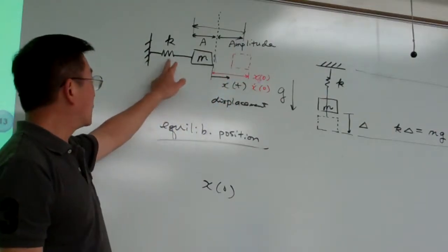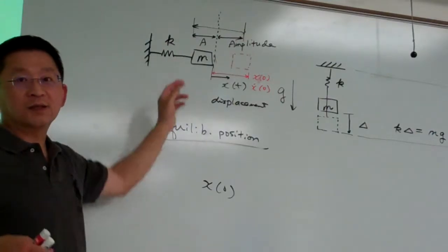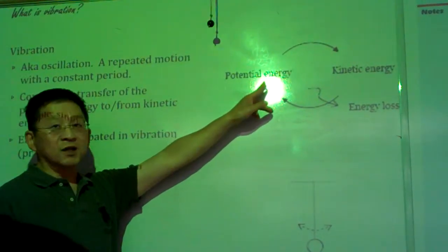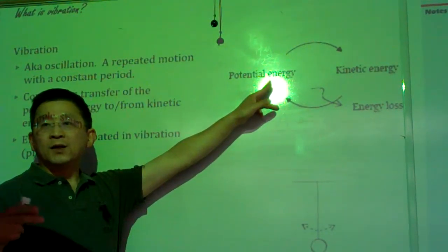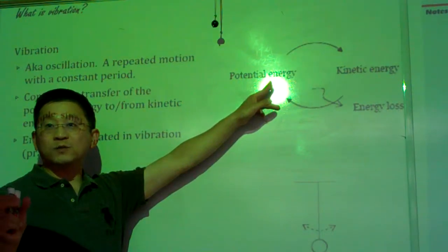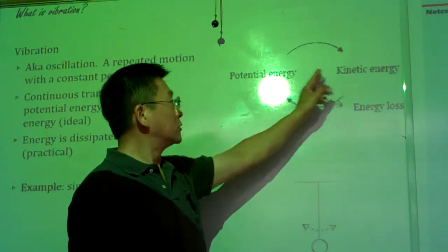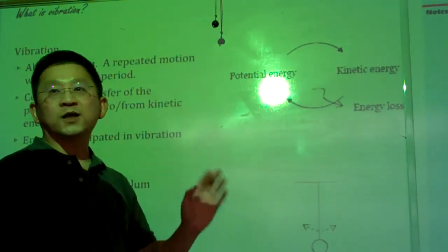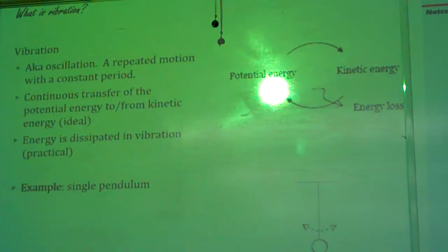Then under that situation, the spring is going to respond to such initial conditions, and the system is going to vibrate. Once the spring has deformed, it has potential energy, and the elastic object is going to recover back to its initial undeformed status. That means the mass block begins going back. So basically there is a buildup between the potential and kinetic energy, the energy transforms into two forms, and that is the way the oscillation starts.